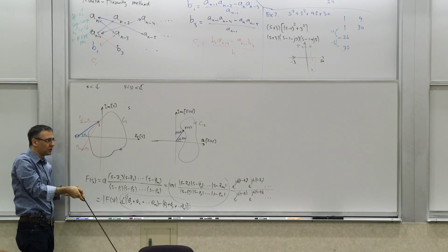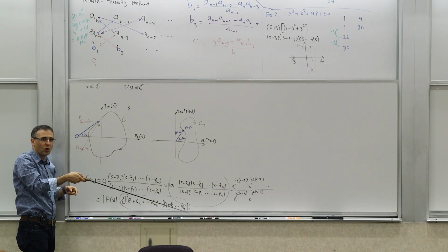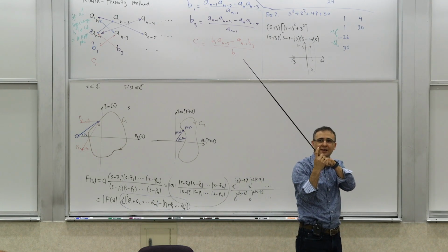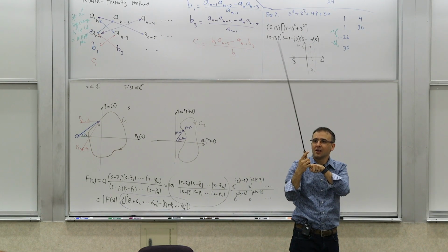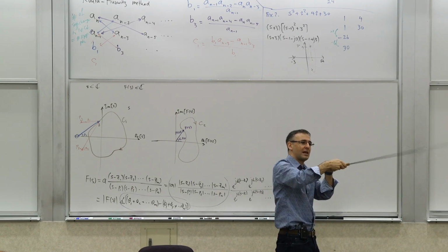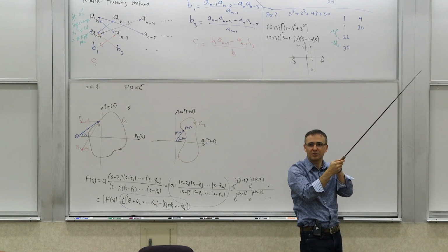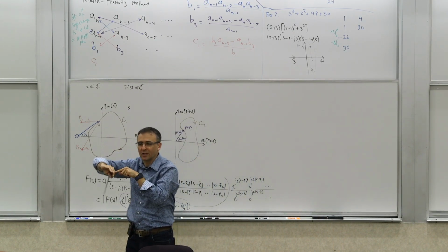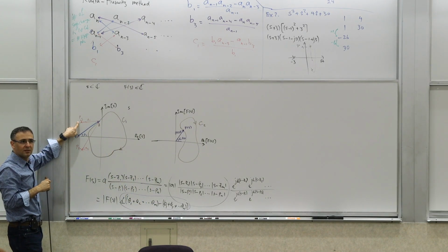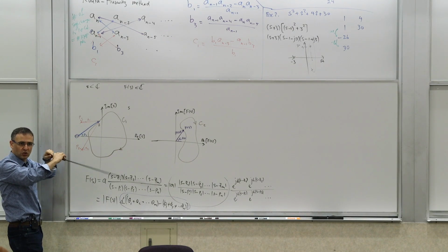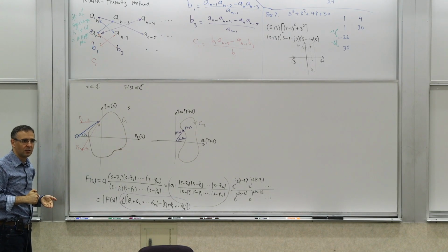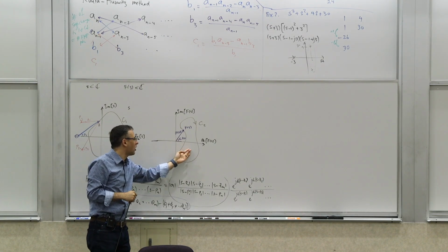So for one closed trajectory, you do some up and down, but you don't do a twist, a full turn, right? So for example, if I had a rubber band attached to the tail of this thing, this rubber band would not have a twist at the end of this process. You bend one way and it comes back, but it's going to be back to where it was. It won't end up with a full twist or multiple twists, right? Same thing with the poles, the phase angle that each one of them introduces. And we know the total phase angle is the sum of these minus the sum of these. So what does that tell us about this contour?